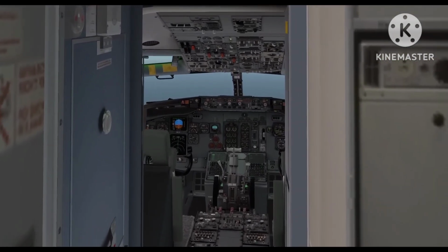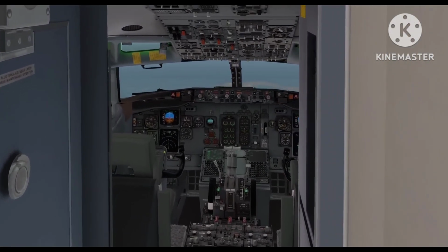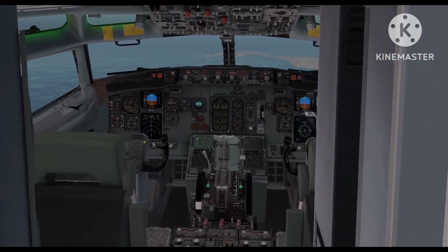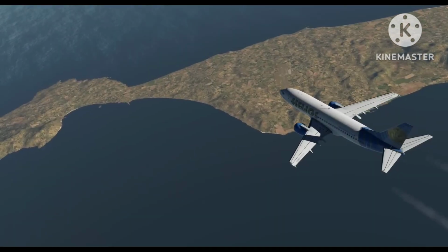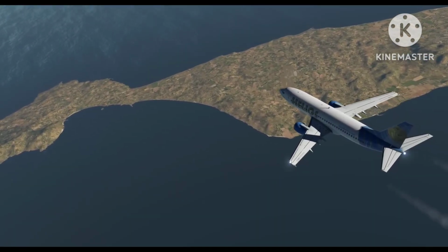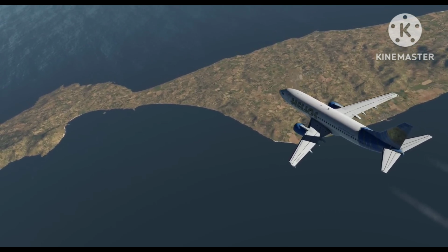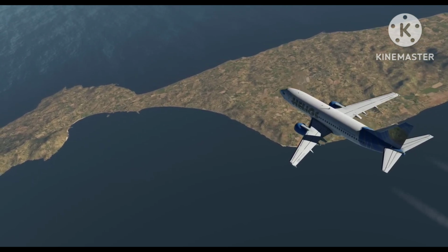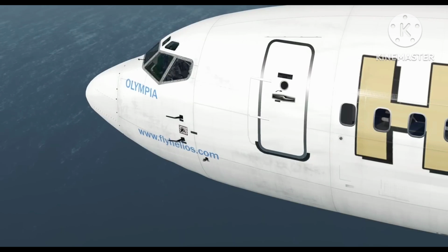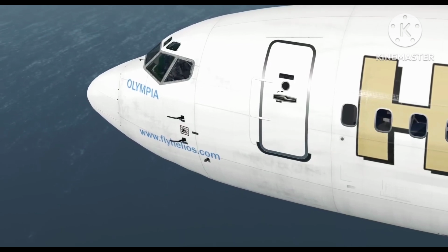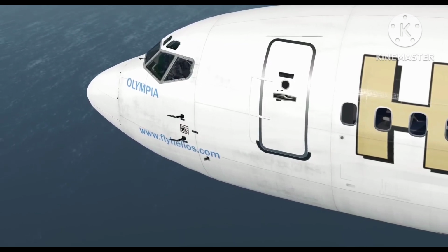They missed another opportunity to catch the error during the after-takeoff checklist, which included checking the pressurization system indicators. As the aircraft climbed, the outflow valve, set to manual, remained open, leading to gradual depressurization. At around 10,000 feet, the cabin altitude warning horn sounded.